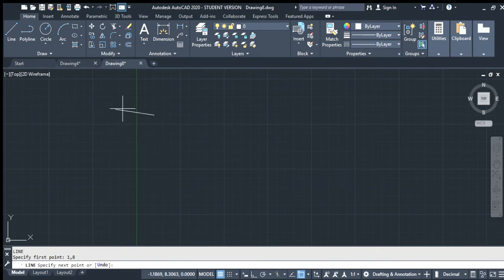This would be 180. I can also do -45 as the same as I can do 315. So 315, -45, they're the same thing. It's just going off of your positive x-axis. So you're basically just using vectors this time. We're going to do at 1, the important thing here is now we hit shift before we hit our comma, and that'll give us our arrow, and now it gives us degrees. So I'll go ahead and put 0 for my degrees, and it gives me 1 magnitude, which is 1 inch in the 0 degree vector. Now I'll do at 4 in the 270 degree.